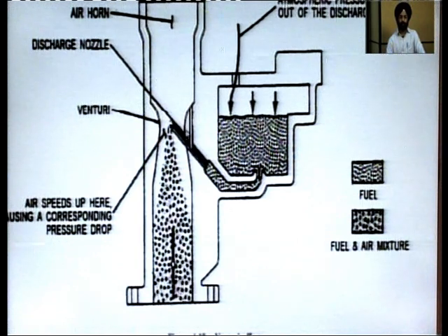So, here we will learn how the fuel is mixed. Now when the suction is there, this is the throttle valve, and this passage is open. Let us first assume that this passage is completely open and a suction stroke has started. The suction stroke means an increase in volume of the cylinder, which will cause a reduction in pressure, which is transmitted here. So, in this whole pipeline, the pressure will drop, and from the outside through the filters the air will rush into this pipe.